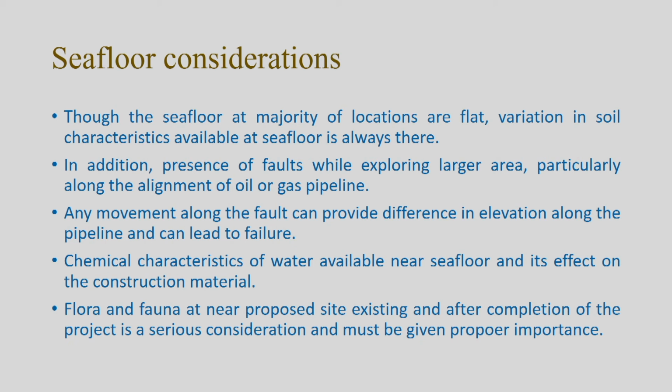In addition, there may be the presence of a fault, identified particularly when you are exploring a very large area along the alignment of a gas or oil pipeline or maybe transmission line cables; you have to also explore the seafloor. What are the possible faults coming along the alignment, and what are the possible movements there, so that your mechanism for anchorage can be designed properly to withstand that particular movement without endangering the safety of the structure.